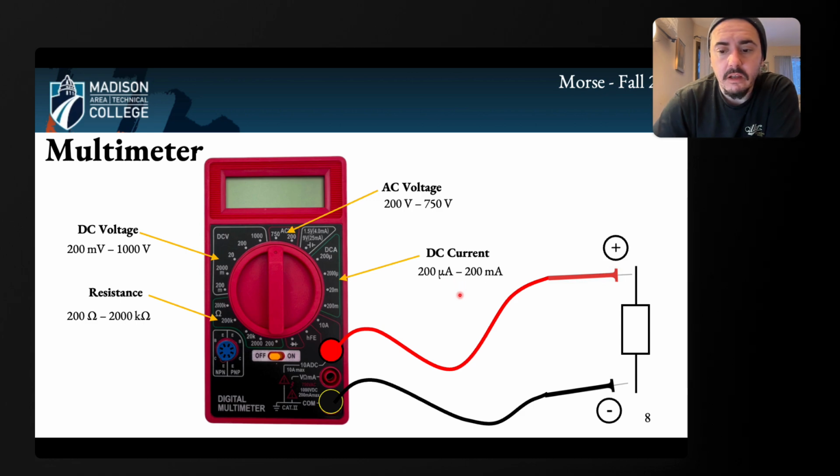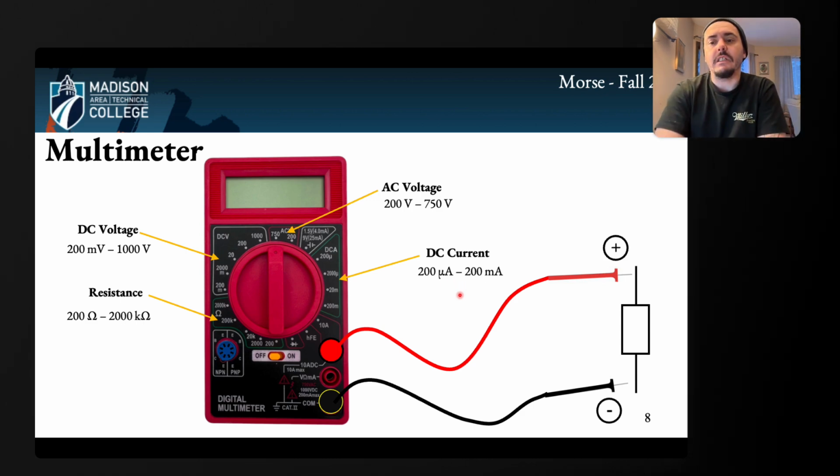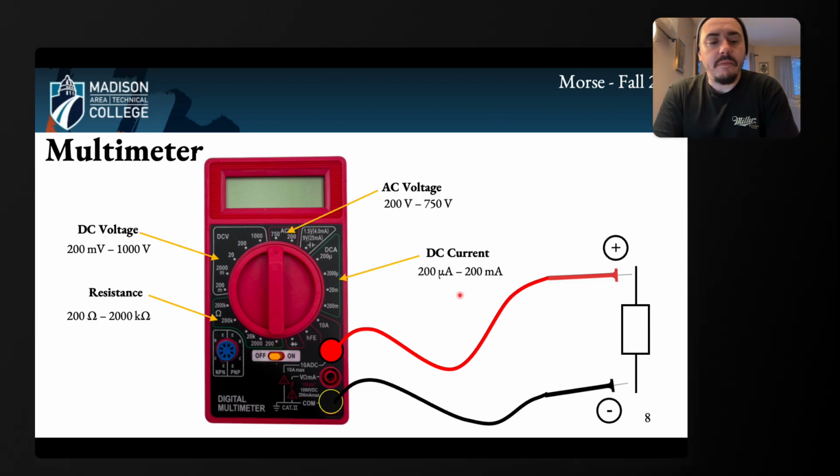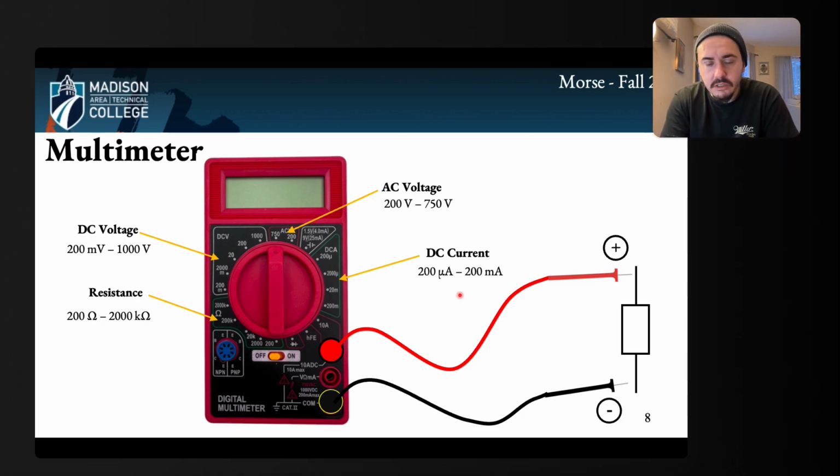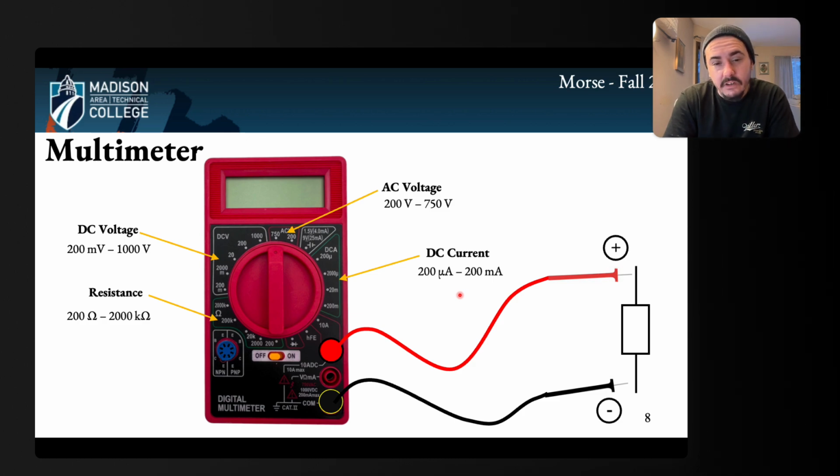So typically, many of these devices and many of these sensors that we're going to look at, they give information, or they're powered by some control component, but basically they run on 4 to 20 milliamps. So if it's being provided 4 milliamps, it's at an off state.